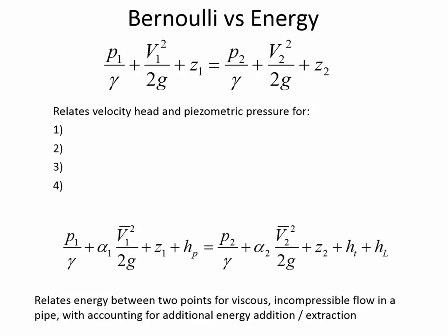A pump adds energy. We'll talk about how it does that. It does it a little bit differently than you might first think. But a pump adds energy, and so that's why we put it on the left-hand side of the equation. These other two terms take away energy, and that's why they're on the right side of the equation. So we've got, again, the pressure at 2. Here's the pressure head term, the velocity head term, the elevation term.